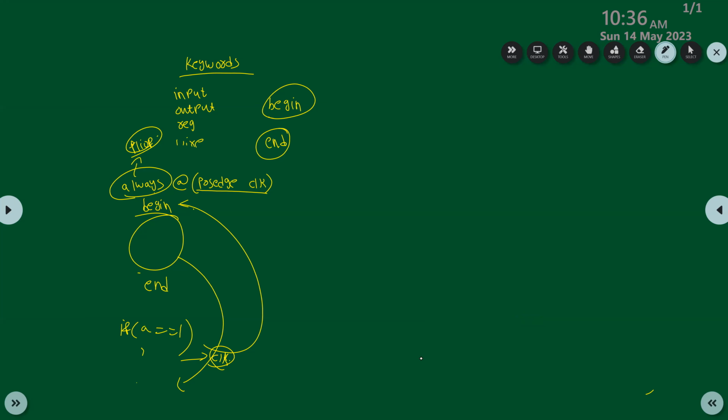So it means if you are declaring a variable W1 and you are not initializing it with any value until 1 microsecond, what is the value? It may be 0 or it may be 1 based on the glitch. So we can treat it as an X.